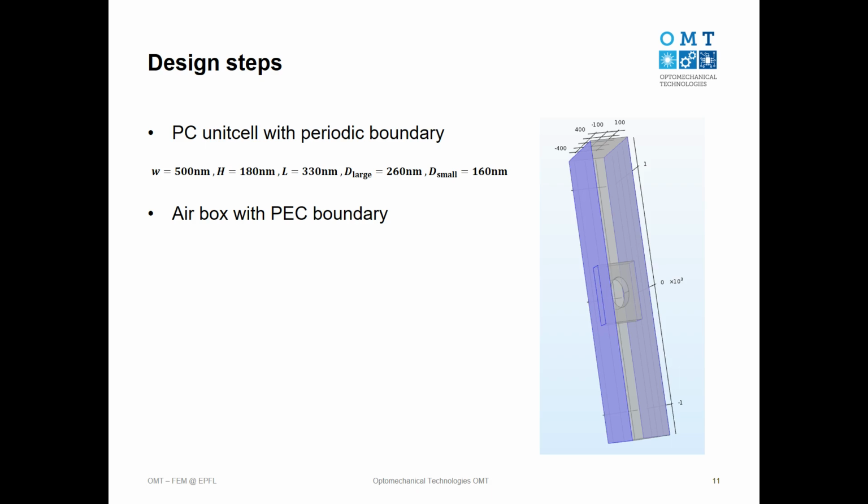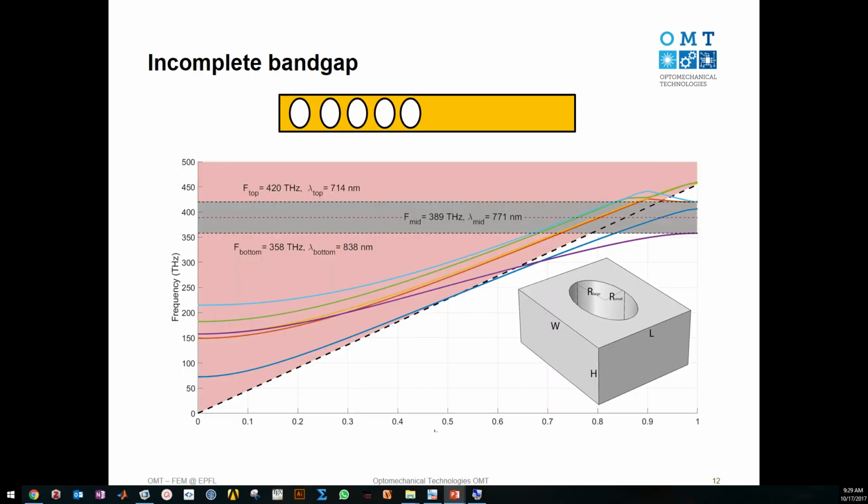Because it's not physical if the mode is propagating inside the light cone. Yes. So will this outcome change if you use other boundary conditions? I don't think so, it should be the same, because I just put this to limit my model and put some boundaries around it. If we make the surrounding a PML, we just assume there is no reflection, so there might be a difference. But we can try, of course.